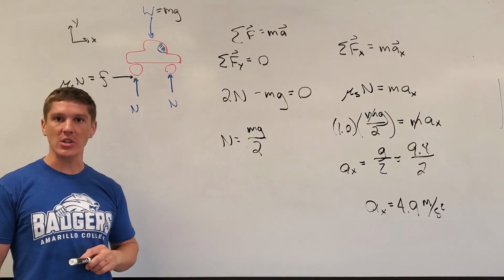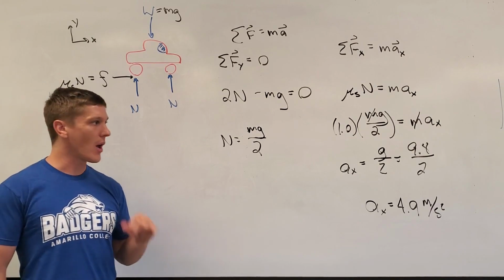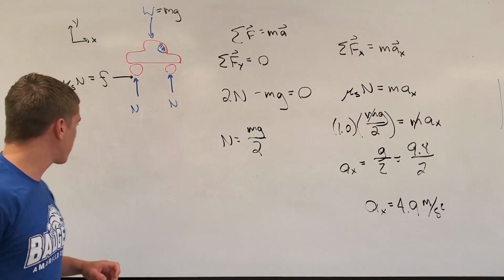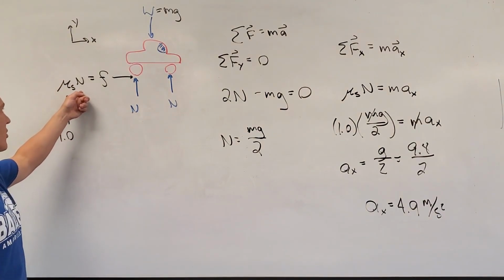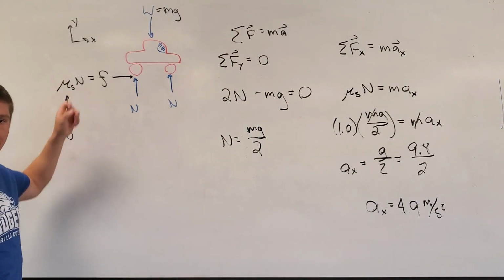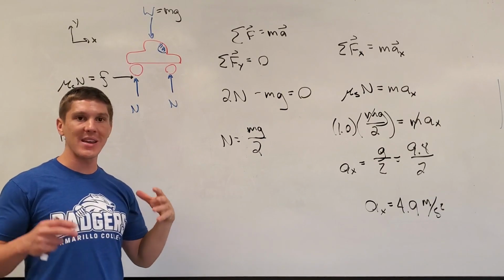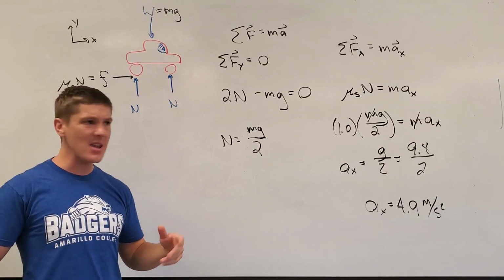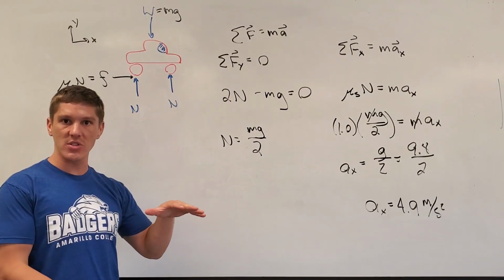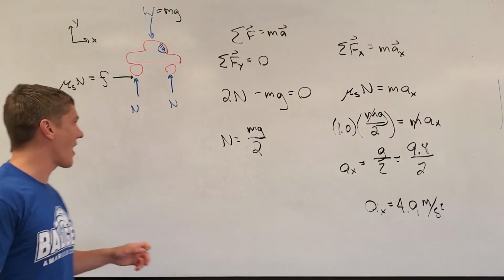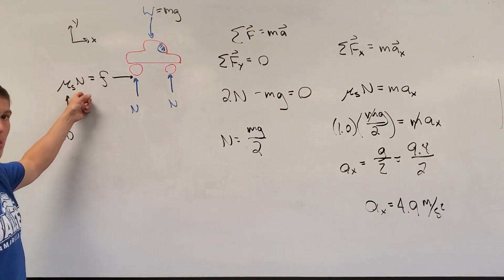How can I increase acceleration? Well, there's two different things that we can do. The most obvious one is we can figure out some coefficient of static friction that's higher than 1, and that may not make a lot of sense, but think about something being tacky or sticky. If you have a sticky surface contact, you can in fact have coefficients of static friction greater than 1.